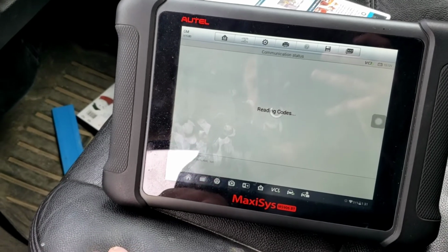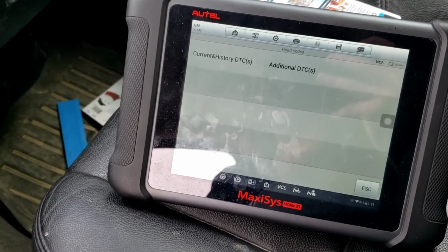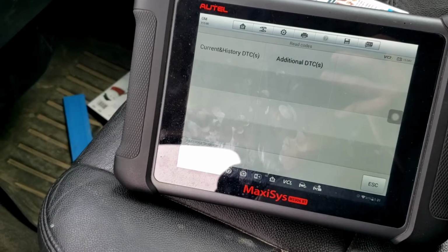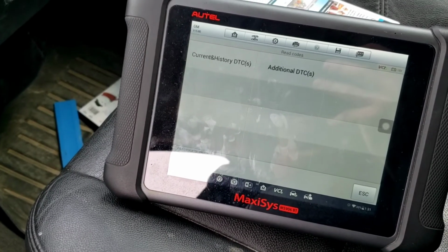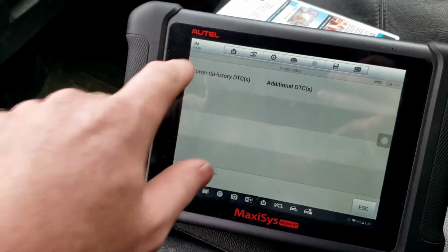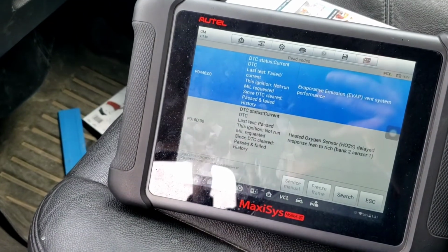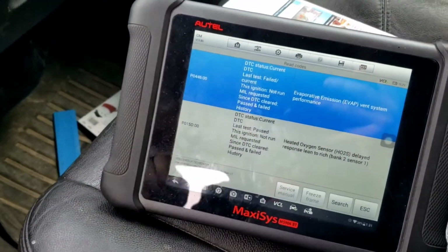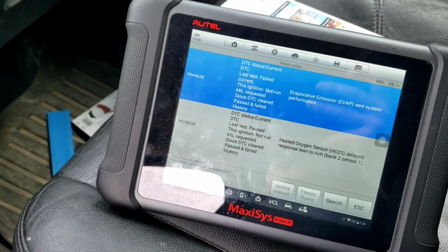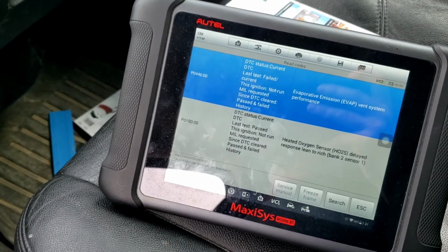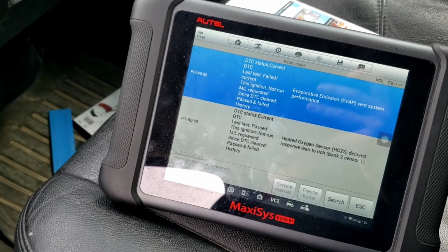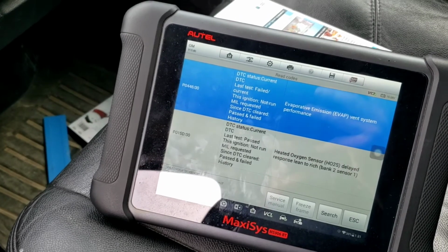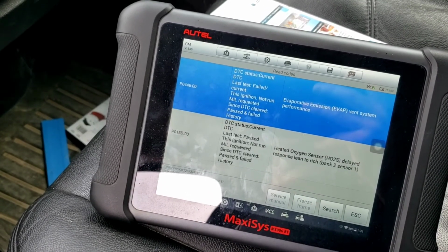What we'll have to do now is go to the back of the gas tank, go to the EVAP vent solenoid and charcoal canister, see if that thing's plugged up, see if there's a restriction in here somewhere. That would typically be where it's plugged up for this code. That's typically what you see, especially if you go down a lot of dirt roads.